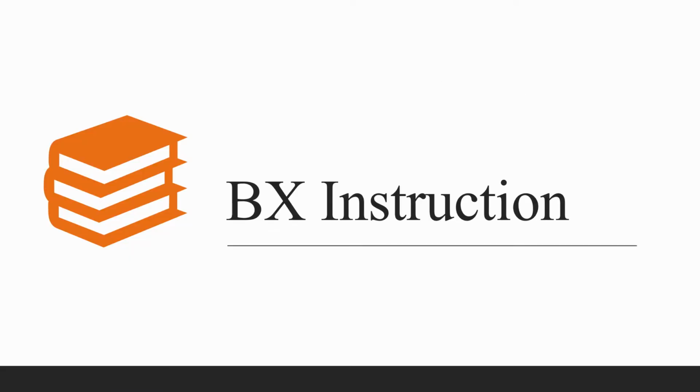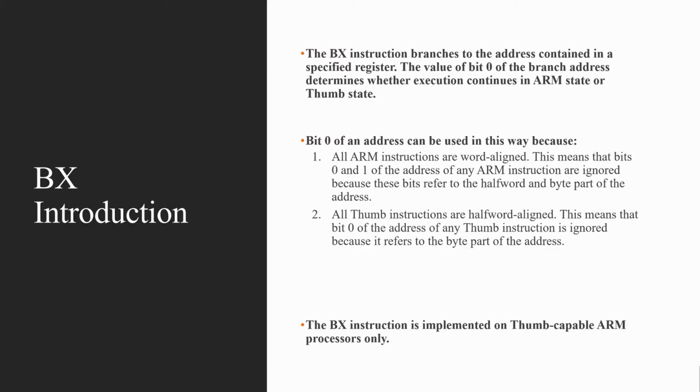Assalamualaikum and very good morning to our lecturer and my friends. Today I want to present about the BX instruction. BX instruction branches to the address contained in a specified register. The value of bit 0 of the branch address determines whether execution continues in ARM state or Thumb state.